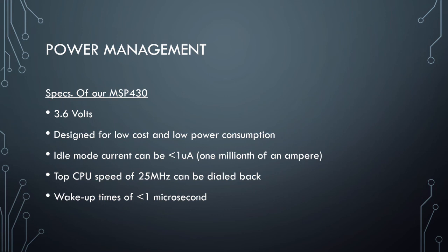So what is your CPU speed? What temperature are you using it at? What's your wake up time? You can adjust some of these features to find that balance between optimum performance as far as execution goes, and balancing battery life or the power consumed.